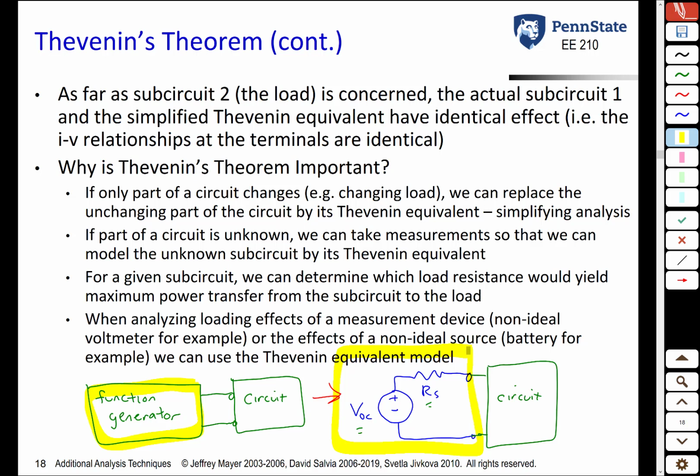Another place where we use Thevenin's theorem, you've probably heard that you can model speakers as resistances. Many speakers are modeled, for example, as 8 ohm resistors. Does this mean that when you have a big speaker, all that it is a single 8 ohm resistor? Of course not. There's lots of electronics inside a speaker. But as far as the rest of the circuit is concerned, that speaker has the same properties as an 8 ohm resistor, so we model it as an 8 ohm resistor. That, once again, is Thevenin's theorem in action.